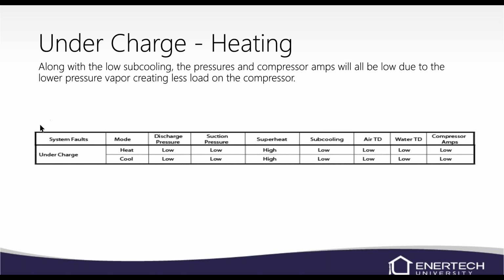In our IOMs, we will list these charts here that will tell you if it's undercharged and you're in heating mode, what will some of the symptoms be? So low discharge, low suction, high superheat, low subcooling, low air temperature difference, low water temperature difference, and your amp draw will be low. And we have these for overcharged, undercharged,